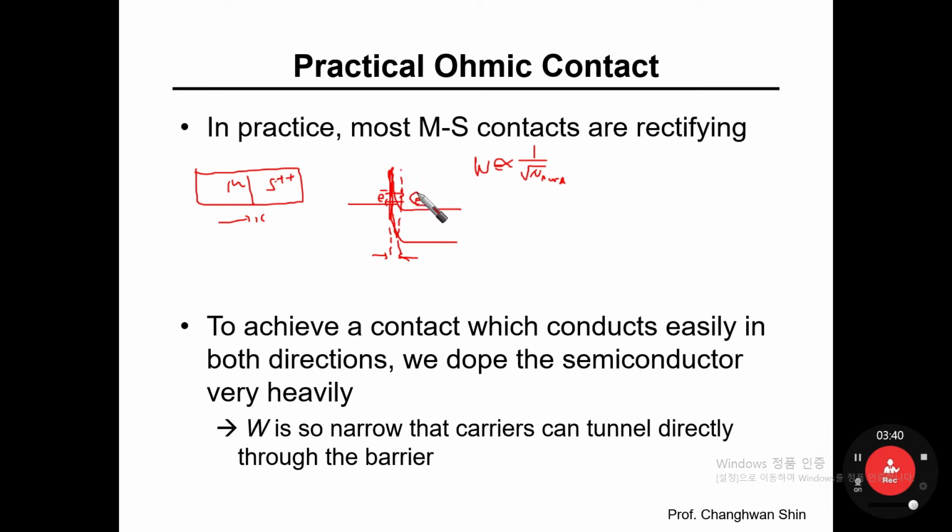From the perspective of electrons in the conduction band in the semiconductor, there still exists an energy barrier height. And from the perspective of electrons on the metal side, there still exists the Schottky barrier height. As we have learned, an electron on the metal side should be excited to overcome the Schottky barrier height, then it can freely move into the semiconductor side.